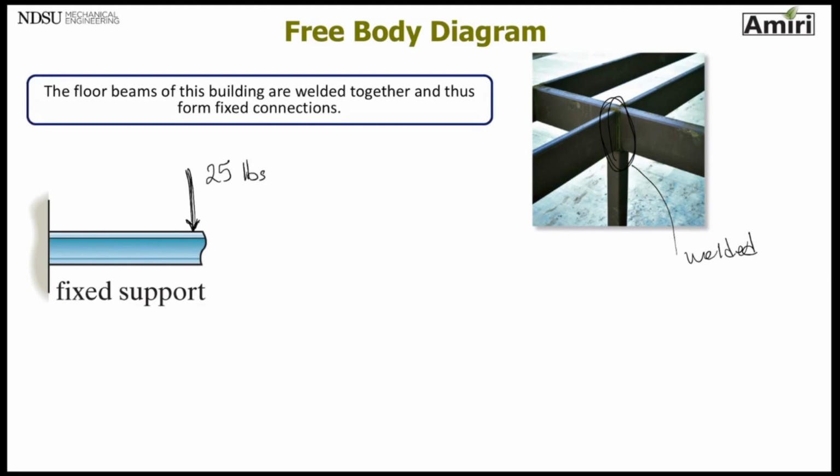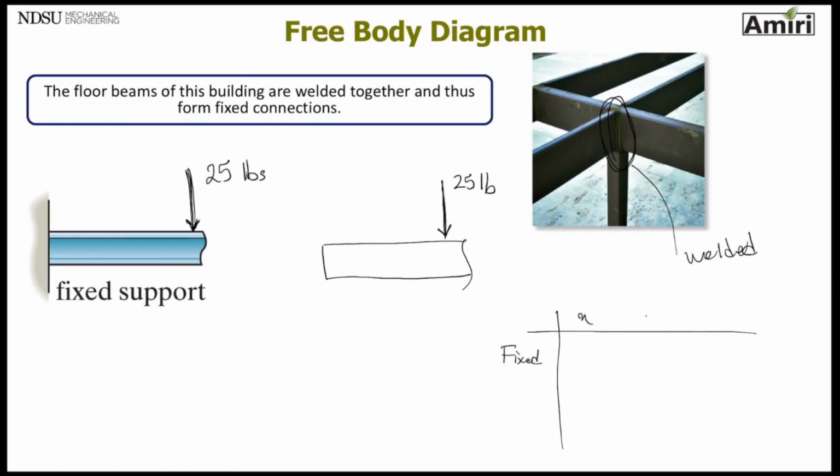And I want to draw a free body diagram. Step 1, isolate an outline of my beam, remove the support, meaning remove that wall. Then put the active force, the forces that are trying to mess up the equilibrium, on there. And now for reactive forces, I'm going to make my little table again, fixed support. I'm going to make X, Y, and moment.